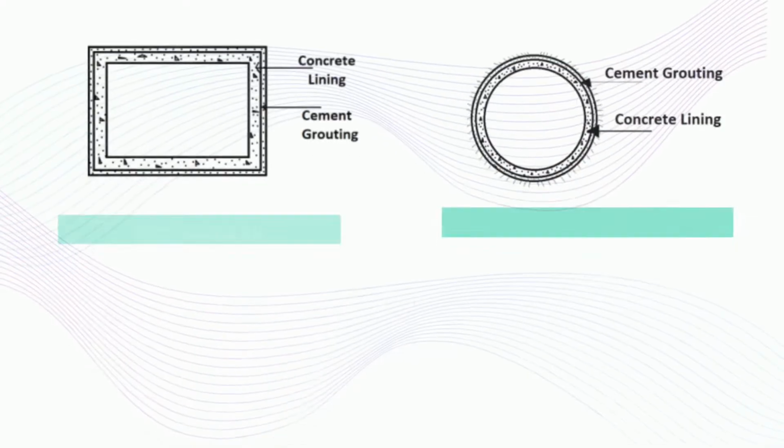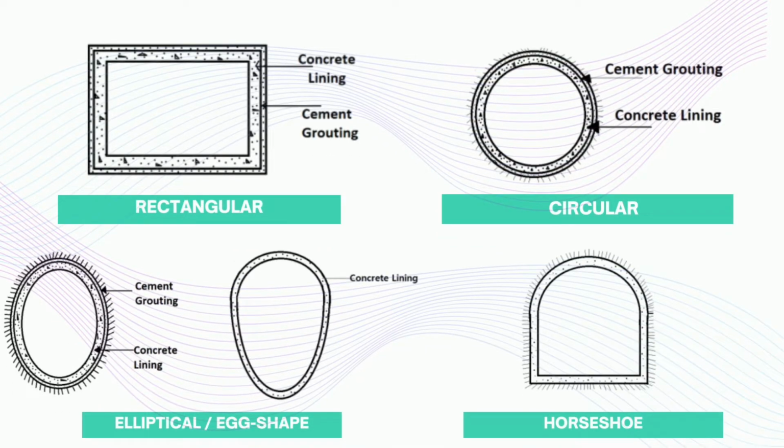So there are few common shape of tunnel which are circular tunnel, rectangular tunnel, elliptical or egg-shaped tunnel, and lastly a horseshoe-shaped tunnel. Each and every shape of the mentioned tunnel has their own suitability in terms of product or item to be carried through. For example, egg-shaped or elliptical tunnel much suitable to carry pipelines rather than to be made as a transportation tunnel. Contrary with horseshoe-shaped tunnel, it is much more suitable to be used as a transportation tunnel like trains and subways.